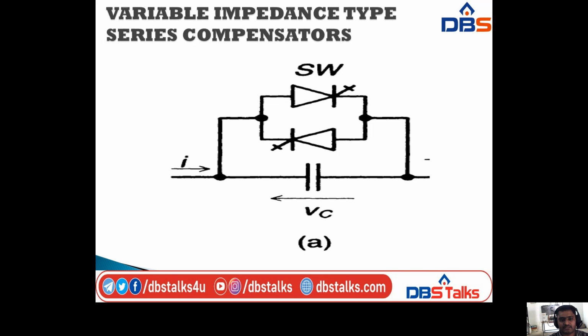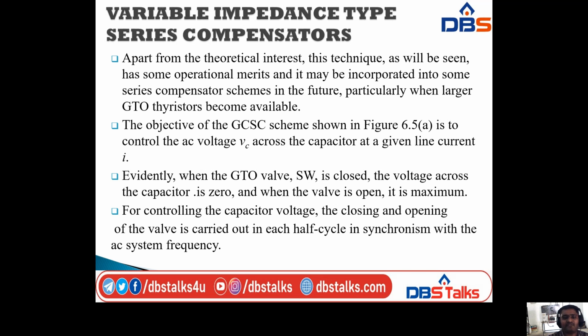This is a diagrammatic representation of that. Apart from the theoretical interest, this technique, as will be seen, has some operational merits, and it may be incorporated into some series compensator schemes in the future, particularly when larger GTO thyristors become available.